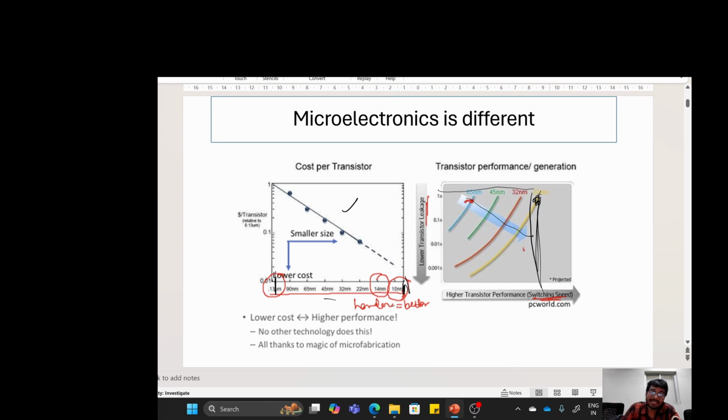If you are decreasing the dielectric thickness, you are also compromising the leakage current, maybe the gate leakage current, or the turn-off current. Let us first see the transistor characteristics once.